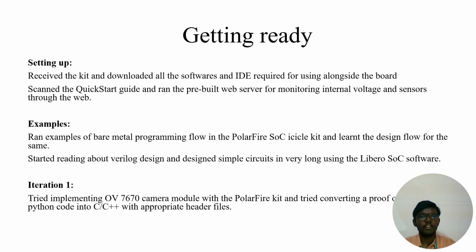So initially we got the kits by the first week of October 2024, and we installed all the software, IDEs and tools required for using the board, and we went through the quick start card, which allowed us to get a good hand with the kit. And then we ran a few bare metal programming examples on the PolarFire SoC Icicle kit to work with the RISC-V cores, and we learned the design flow for the same. Alongside, we began learning HDL and Verilog design for simple circuits using the Libero SoC software.